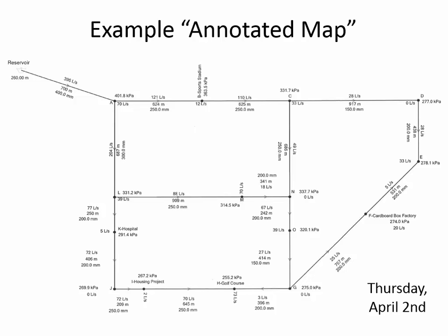And the peak condition is whatever you determine is the design flow rate at each of these either loop locations or external locations. Which is this? Is this the static or is it the peak? That's right, it's the peak, because we see water is flowing through the pipes, and then the other sort of clue is that the pressure is nearing the lower limit. What's the lower limit for our design?